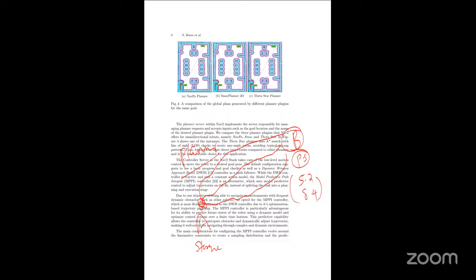The other input is which algorithm should be used: the planner plugin. In Nav2, there are three different planner plugins. NavFn planner is the old planner. This was using the Dijkstra algorithm: simple, reliable, trustable. The disadvantage was that the path has more turnings.